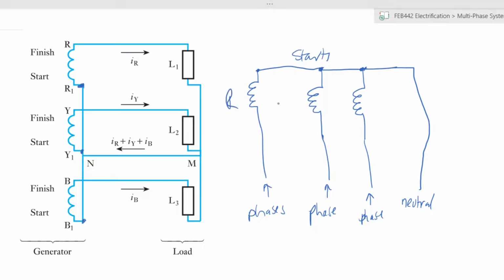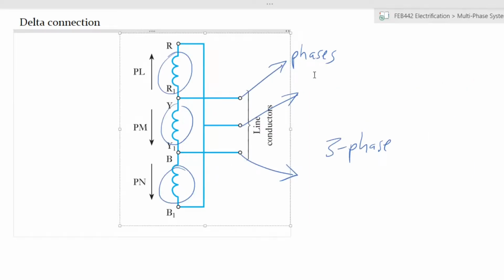So you have your winding, let's call that red, let's call that blue, let's call that yellow. All the starting points of your windings, you connect them up together, and the joined up parts of the windings will be connected to what you call the neutral. So what you now end up with is you have 3 phases and you have what you call a neutral wire. And this may start to be familiar to you in that usually when you have power being transmitted, you will usually see either 4 wires, or, for very high voltage connections, you will see 3 wires or 3 phases. And this is what we are representing here.